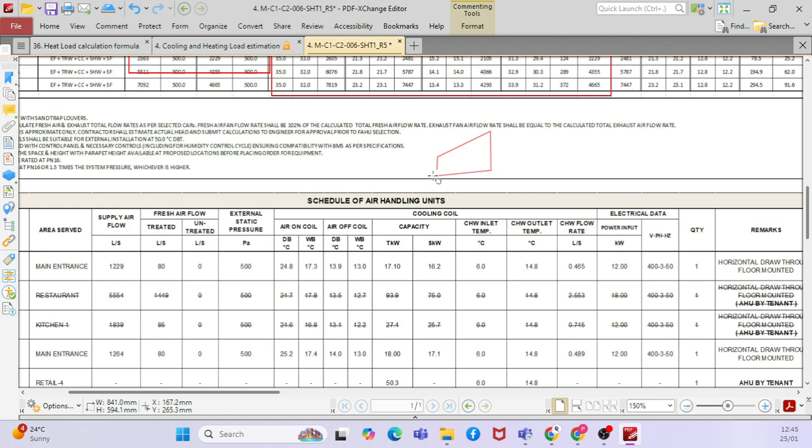Okay, this is the psychrometric chart, right? If you go to the psychrometric chart, you have different readings. You have a dry bulb temperature, a wet bulb temperature, then a humidity ratio, relative humidity, everything, right? Yes, sir. Okay. From the psychrometric chart, you can plot the air on coil temperature, say, for example, 24 degrees Celsius and 50% RH.